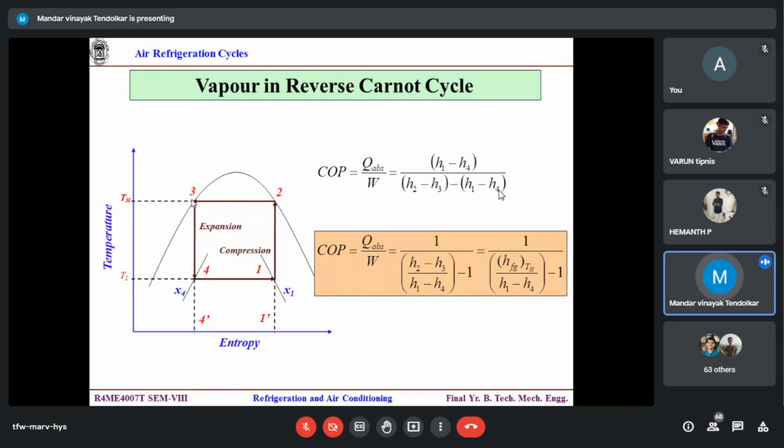Gas expansion is very easy. Liquid expansion is very difficult. So even if it follows a certain expansion process, what is the guarantee that it will be the isentropic one? That is the practical difficulty. So I said you can achieve up to 99%.